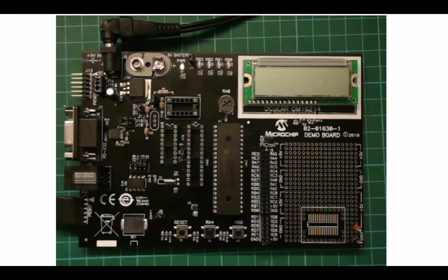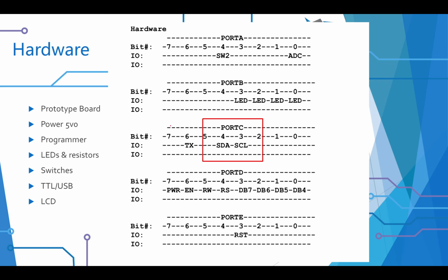So effectively, I've connected it to my GLCD. That's here. Pretend it's here. I've connected to RC4, RC3, and I've pulled off a ground connection and a 5-volt connection up to my GLCD. The rest of it, we won't be using. Well, we'll be using the pot, actually. Lots of capabilities in the microcontroller. As I just said, I've connected up the SDA and SCL, the serial data and the clock line, to the GLCD.